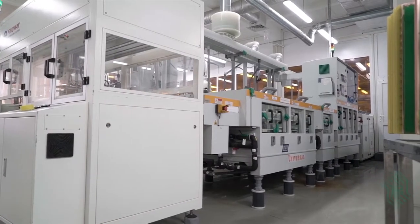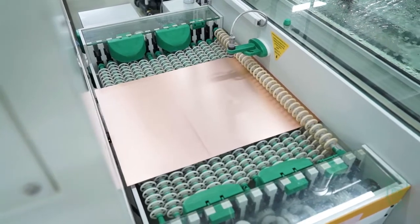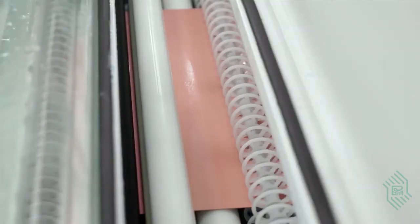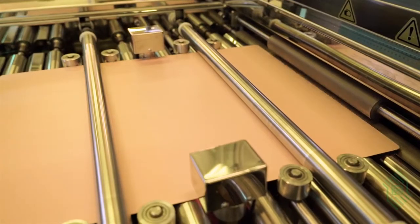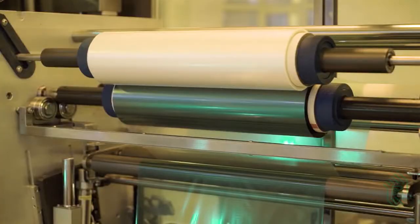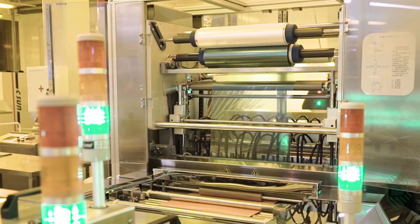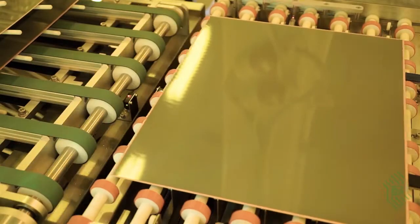The inner layer imaging process of a multi-layer PCB consists of the following stages. At the first stage, the inner layers pass through the chemical preparation line. A roughness develops on the surface of the copper, which is necessary for the best adhesion of the photoresist. At the next stage, the panels pass through the automatic lamination line. The dry photoresist film is applied on the panels using hot rollers.